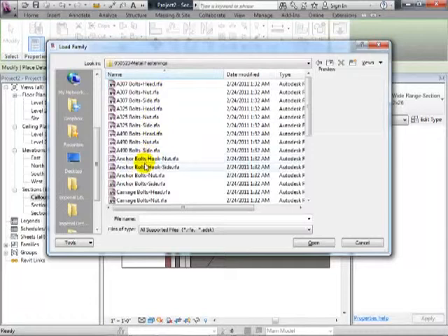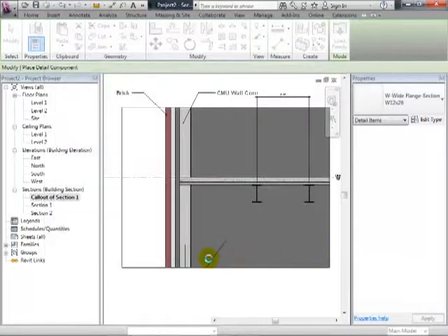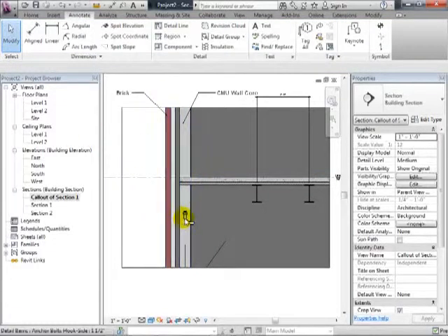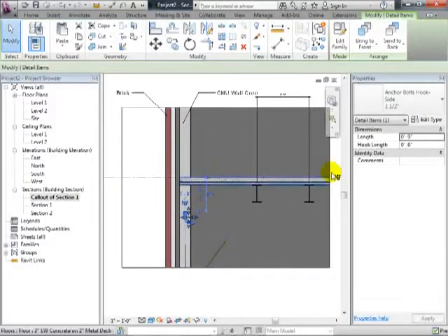I'll find bolts and anchor bolts and things like that. So if I want to put an anchor bolt in there, I can grab this detail component. Again, it's only a 2D object, but it has a little bit of smarts to it. I'm going to put it in a nonsensible place just so I can show it to you. But here it is. It's a 2D object, but it still is parametric.